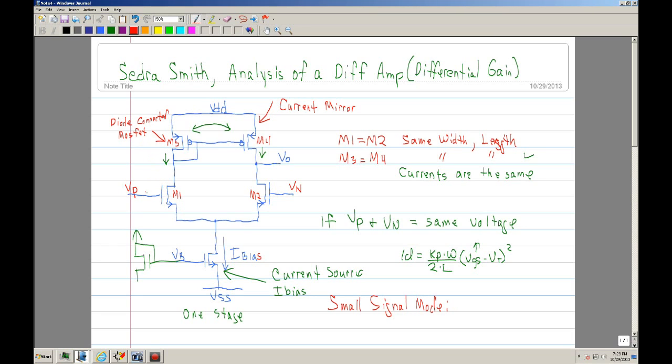If you put a little wiggle here, a positive wiggle, and if you have a differential, you're actually going to get a negative wiggle. This will be 0, this will go in the negative direction, and say that's 0, this would be positive. By the same token, if you swing negative, then this will swing positive. And what I'm saying is that the voltages at the inputs are going to reverse if you have a differential. Okay. Now, what does that do? Well, because one goes up and the other goes down, and vice versa, the voltage at this node stays the same.